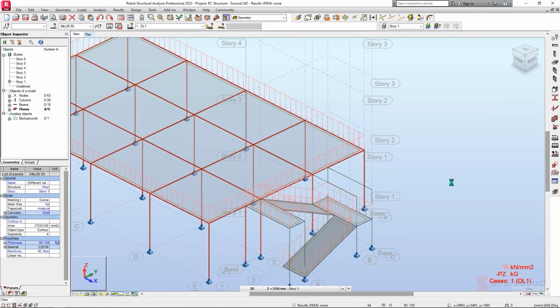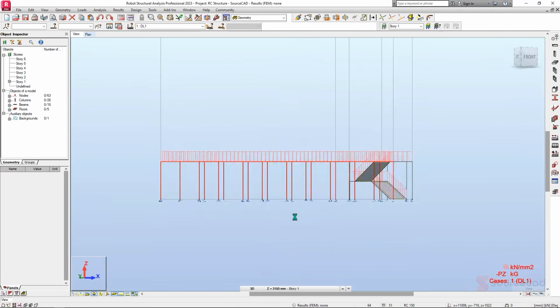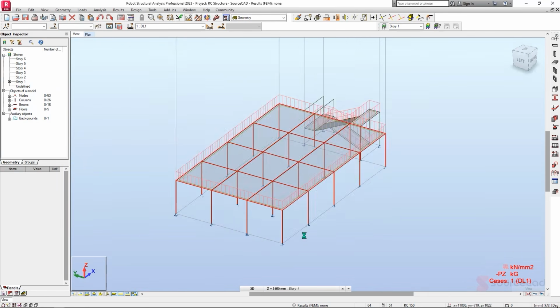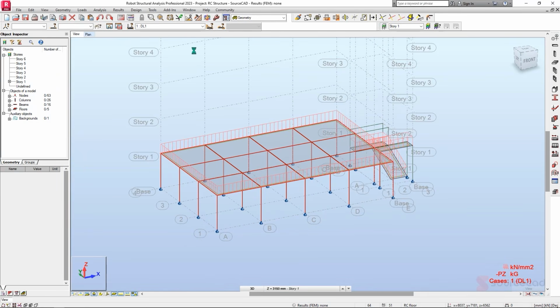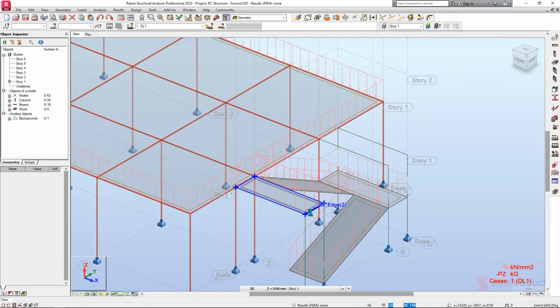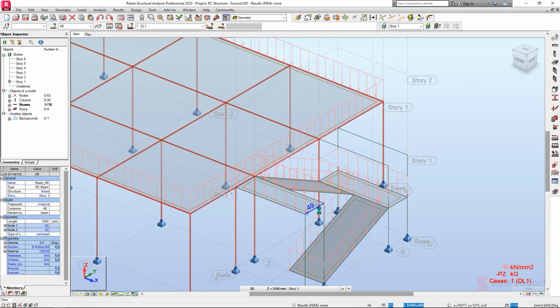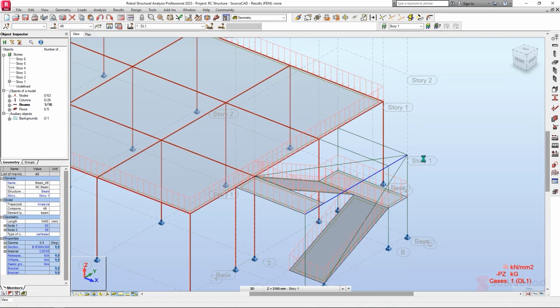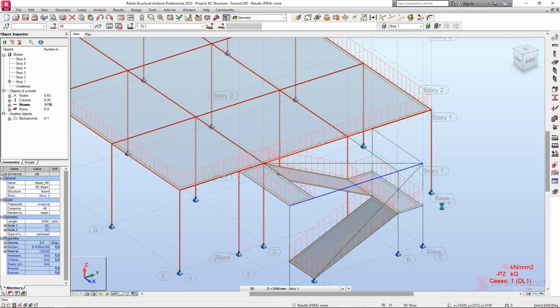After doing our load application and we are confident about how our structure is, we can just run our first calculation analysis. And it's quite easy. So what we first do, we save our drawing. So click on save. And even before running, I clearly see that I would like to extend this specific beam that we have here. So this beam member, I'd like to extend it from this point to this very end point. So it has moved everything.